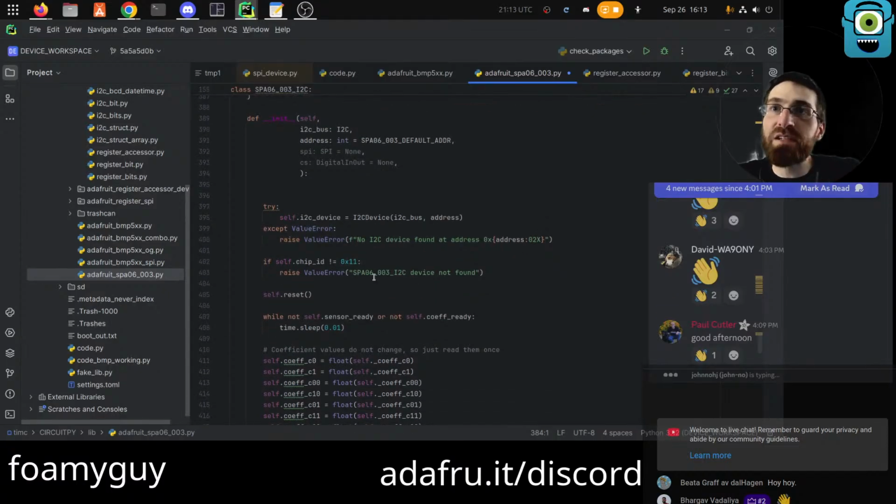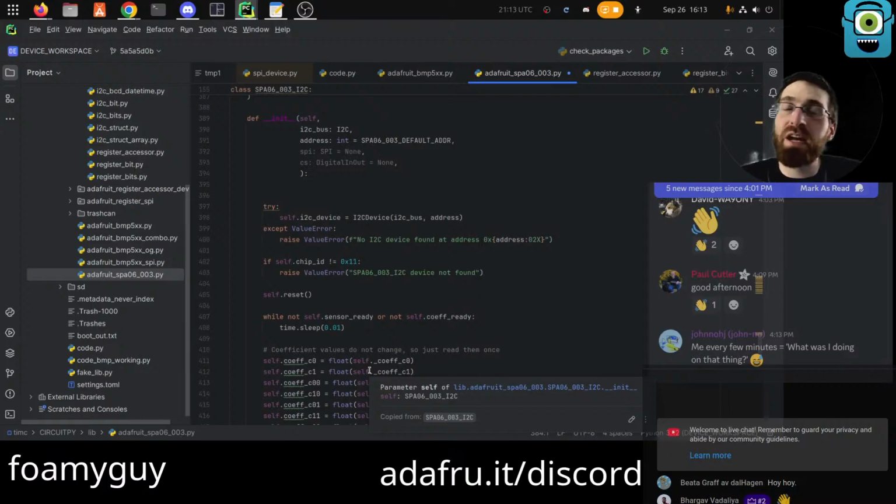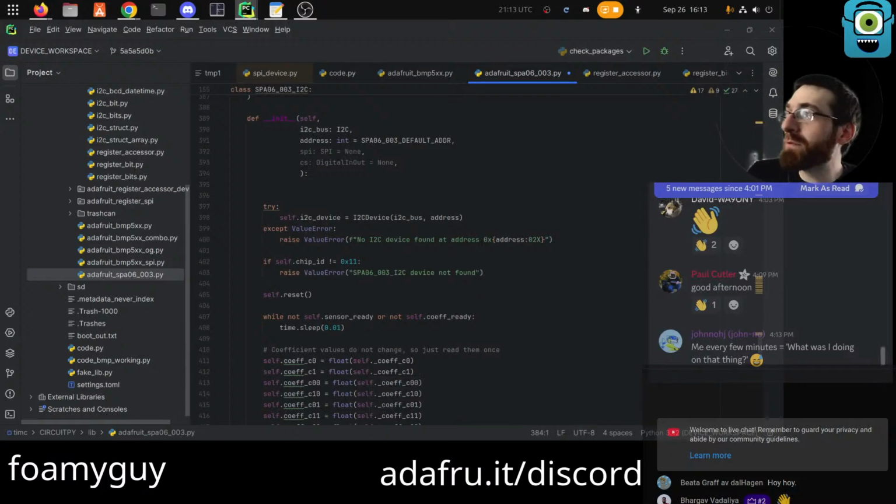I ended up finding that issue with the bit shifting by looking at the traffic on the bus. Lemore showed me the debug flag in Arduino so that I could look at all the bytes that are being read and written over the bus, and I happened to notice there was a weird extra write that was happening after the oversampling was set that my code was not doing, and that's what led me down the road to find that.